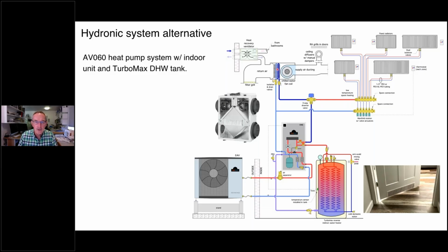And you can see in this case, the heat recovery ventilator is also tied into the air handler. So our supply air ducting is dual purpose. It's there to supply cooled, dehumidified air when we're operating in cooling mode, and year round, it will supply fresh air. So we're getting double usage out of the supply side there.